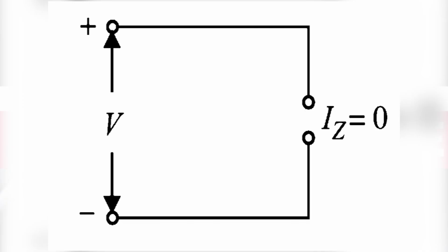So, the following figure shows the equivalent circuit of a Zener diode in the off state. The first figure that we have seen shows the equivalent circuit diagram of the Zener diode in the on state, where the Zener diode was denoted by the voltage Vz, or simply a battery or a voltage source having the value Vz. But in the off state, the Zener diode is denoted as an open circuit, since no current flows through it.